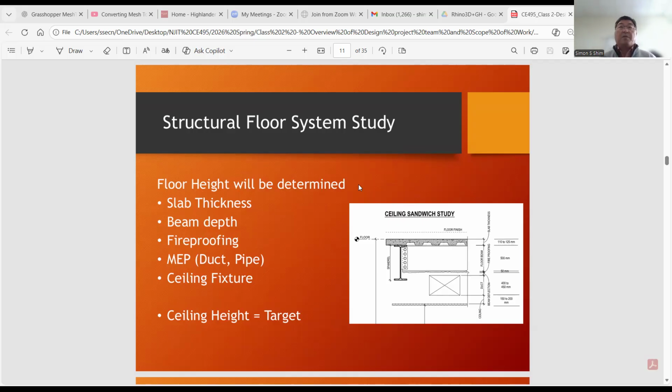So a higher ceiling means a more premier office. For class A, 14.6 feet is the typical floor-to-floor height. In our design practice, maybe we can round up to 15, but 14.6 is class A worldwide. Class A offices constructed recently worldwide follow this kind of ceiling height.